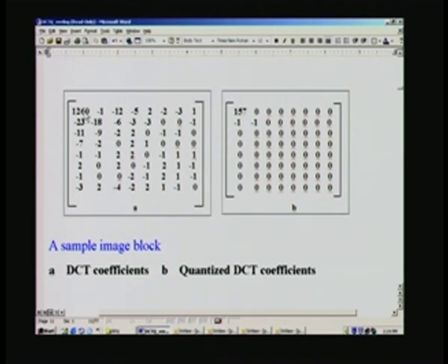No. If you multiply 8 into 157, I think it is 1256. So you started with 1260, but when you reconstruct, that is what is called reconstruction, you do not really recover what you have. Naturally quantization is responsible for this, because we are quantizing by 8.